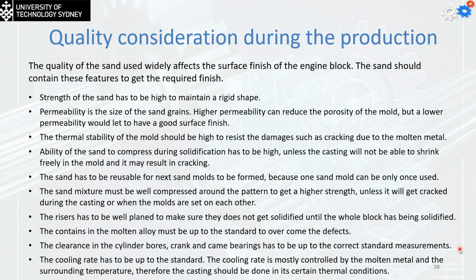The sand mixture must be well compressed around the pattern to get high strength, otherwise it will crack during the casting or when the molds are set on top of each other. The riser has to be well planned to make sure that it is not solidified until the whole block has been solidified. We just remember this point multiple times.